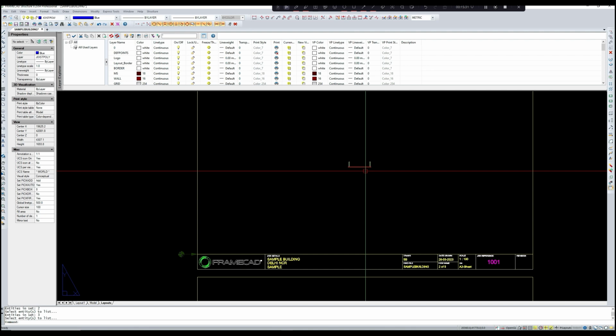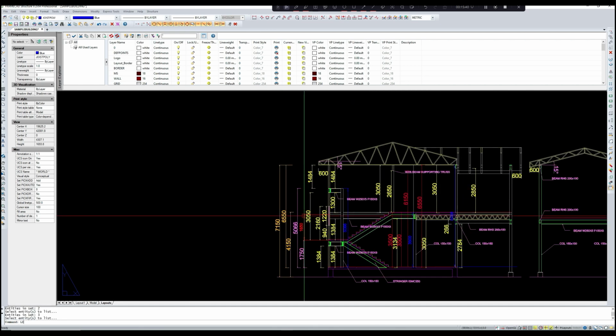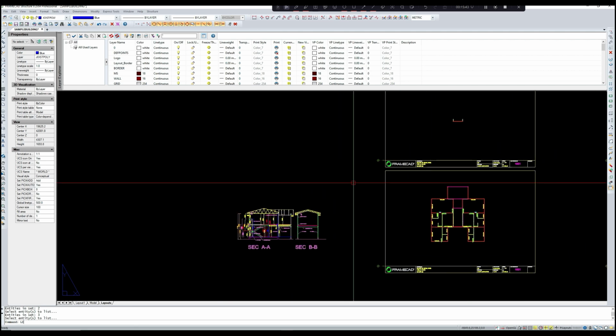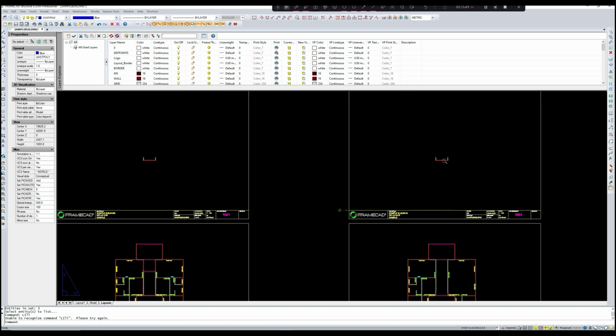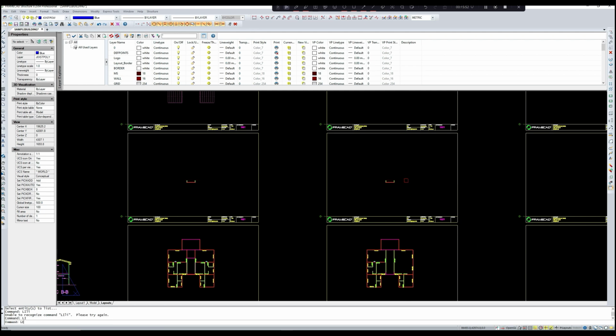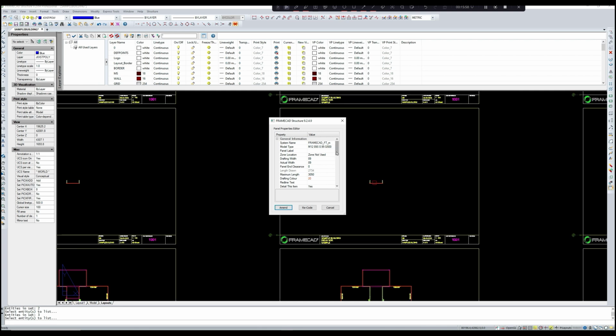These walls at landing level above the top level cantilever shall have a height of 1484 and reduced level shall be 5066. So let us list them and set it. List, set them as reduced level 5066, 5066, no, 1484, amend.